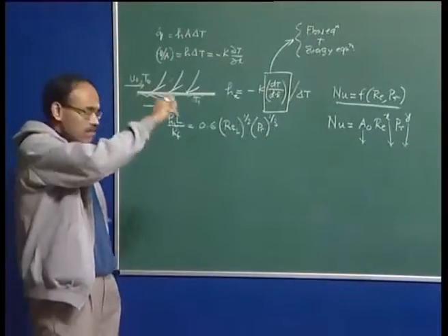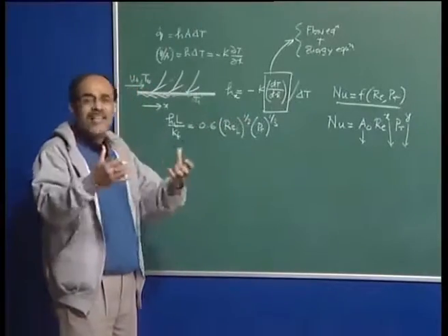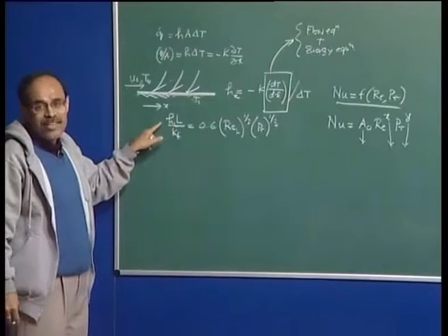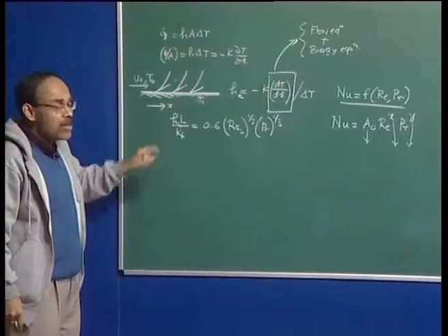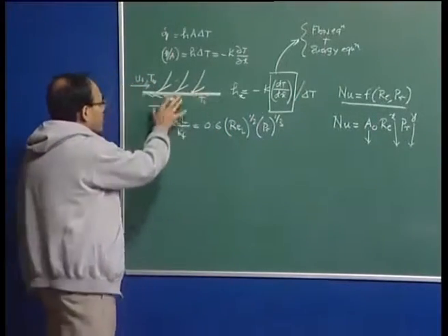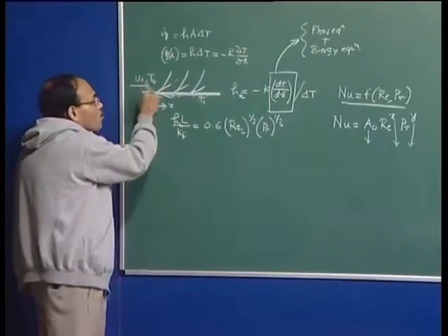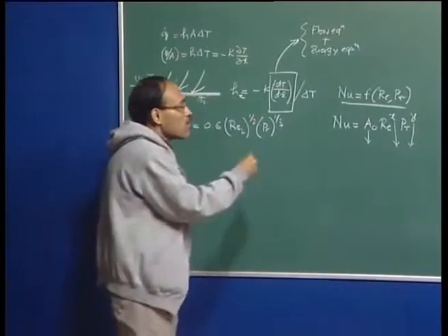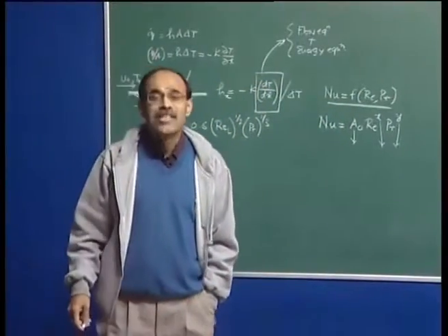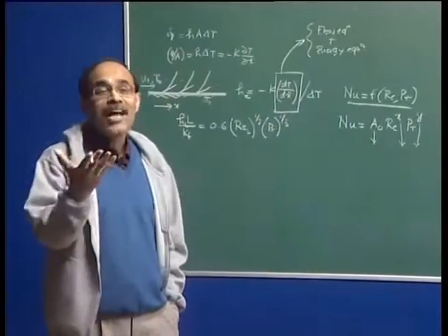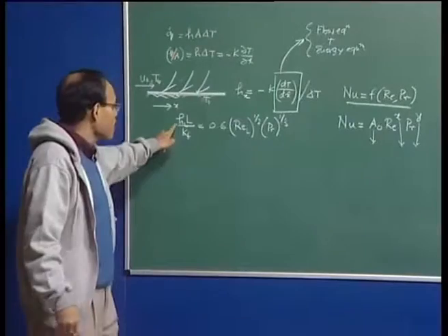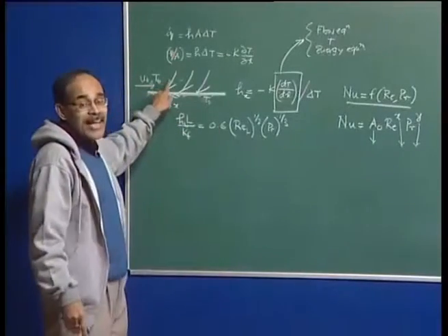So, we try to take correlations from the literature and make certain assumptions and try to obtain a first hand estimate of the heat transfer coefficient, which may not truly be applicable. And also one more important thing is that this sort of correlations are developed for flow of air over a flat plate, okay, but in the case of steel making, we require correlations which would be applicable to molten steel flows, and as you all know, molten steel has a largely different Prandtl number than the normal common fluids like air, water, etc.